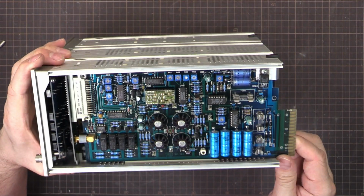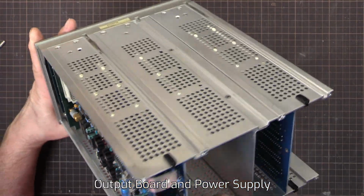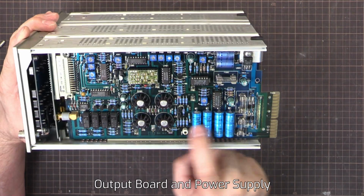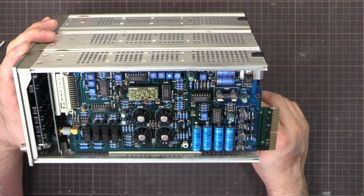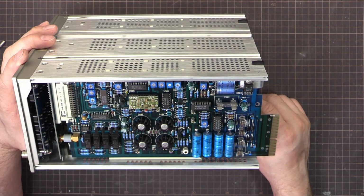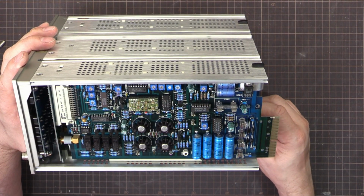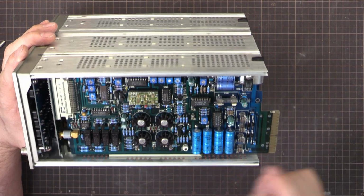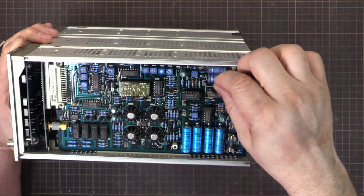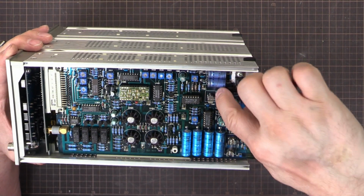Other side. Oh yes, we have got some interesting capacitors here. These ones, they're Philips. We will definitely be testing some of them. The Philips ones like these are known for going bad in a lot of equipment of this vintage. Tektronix benchtop multimeters, yeah, they're a known thing in there. There's a lot of equipment where you see these and they've been replaced on site. Yeah, these are Philips as well. Vishay, I believe, have a similar looking capacitor that's wrapped in blue plastic, but these definitely say Philips on them.